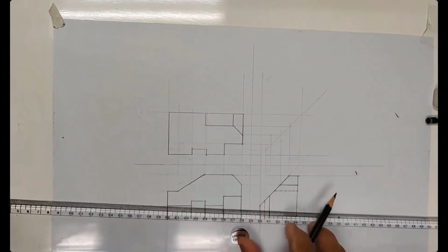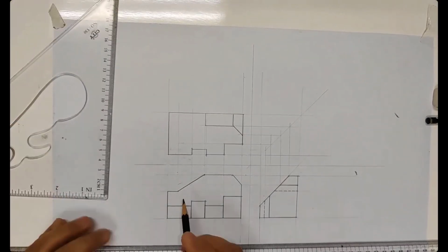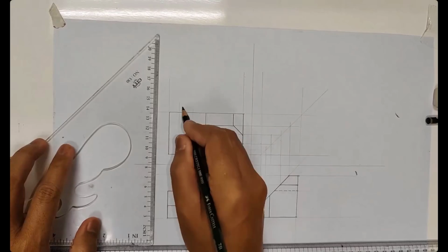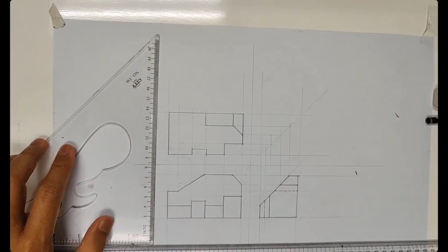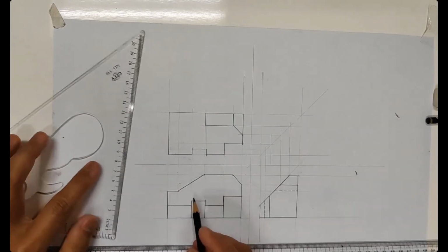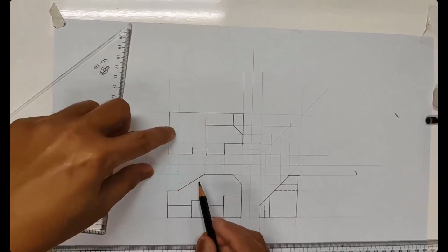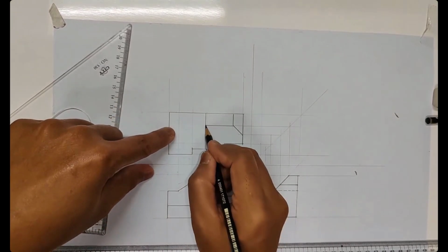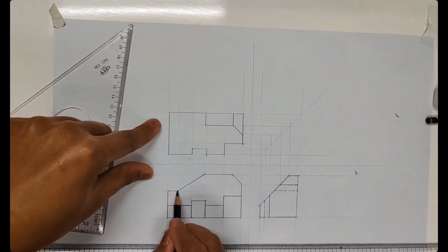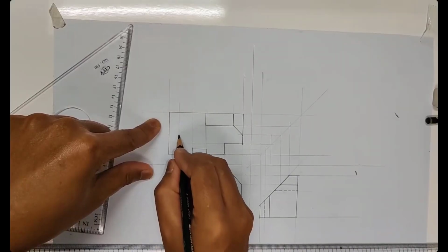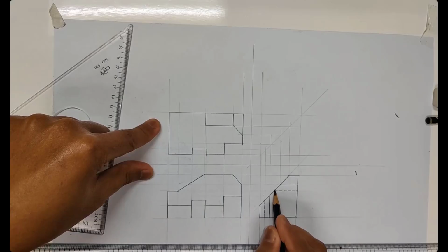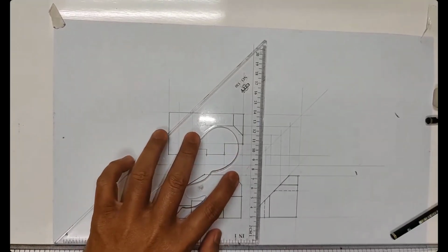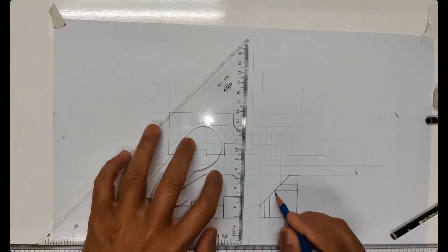So what about here? What about here? Where is it? Which corner? Can you see I have the corner point here? I already have the extension line. So where is it? What about this line? Where is another guide? Are you watching or not? This line, front view, top view, this point is this point. So this point, where is it? Yeah, I already put that. We need to use intersection. Can you see we have the intersection at this point? Side view. This is the hidden line at the back there. So using your 4H, this is a point there.